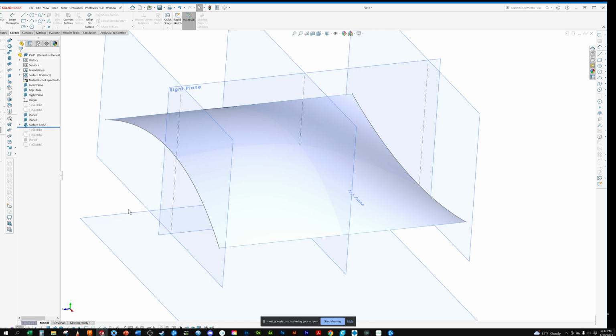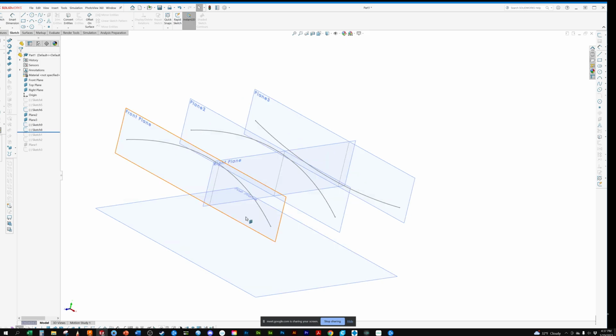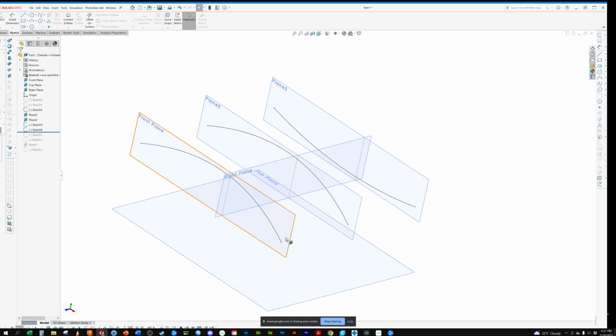Okay, so as we continue, we are still missing any kind of control along this outside edge. So let's come back, and we're going to delete this. Because I copied all these sketches, I know that all these points are in the exact same position.